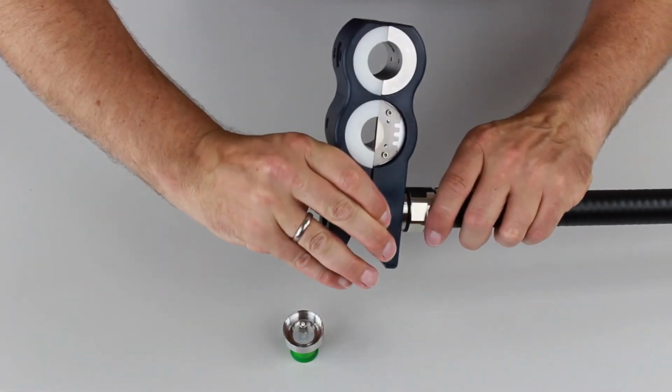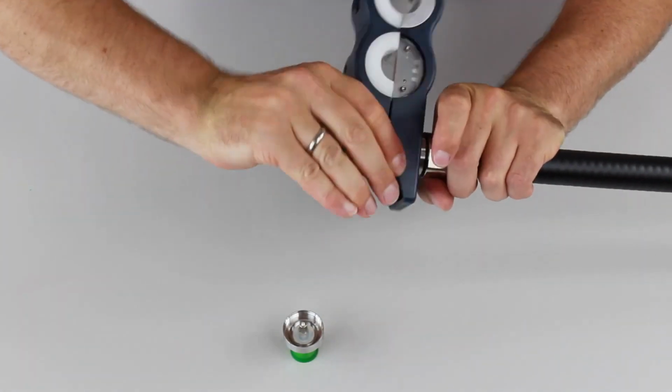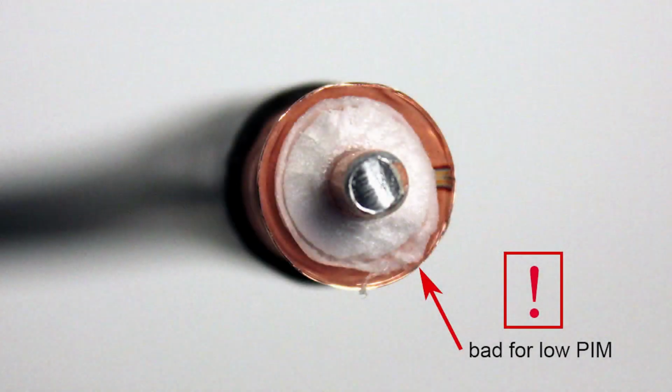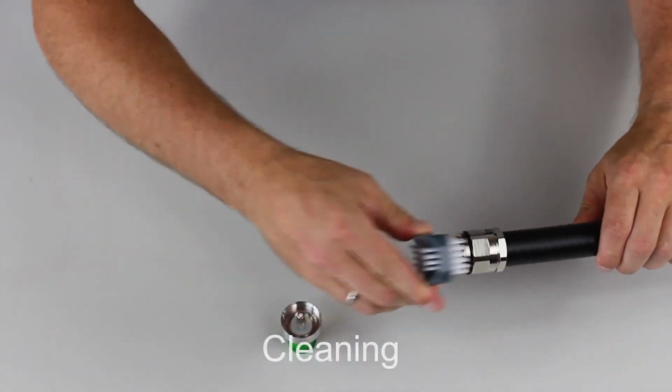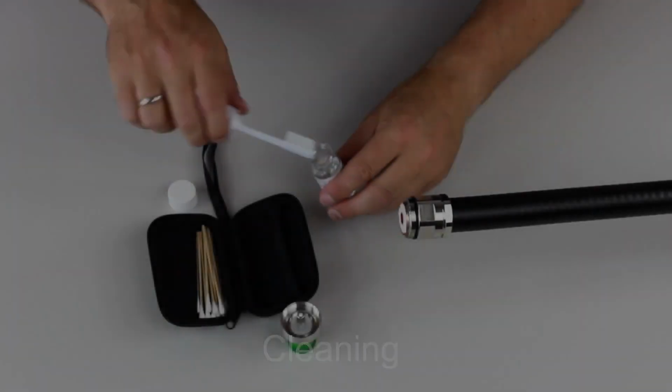It is essential that there are no dielectric residues on the widened copper outer conductor for a low PIM connector assembly. Remove any residues if necessary and take care not to scratch the conductor. Thorough cleaning is essential to enable PIM-free contact.